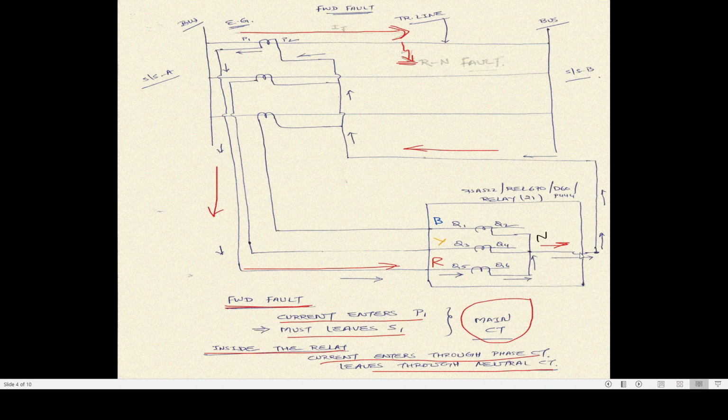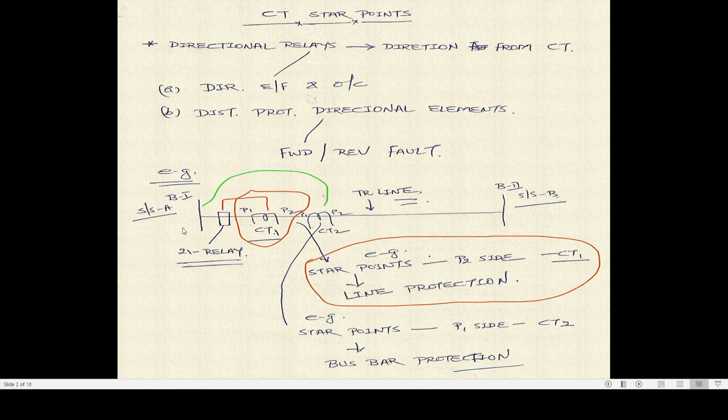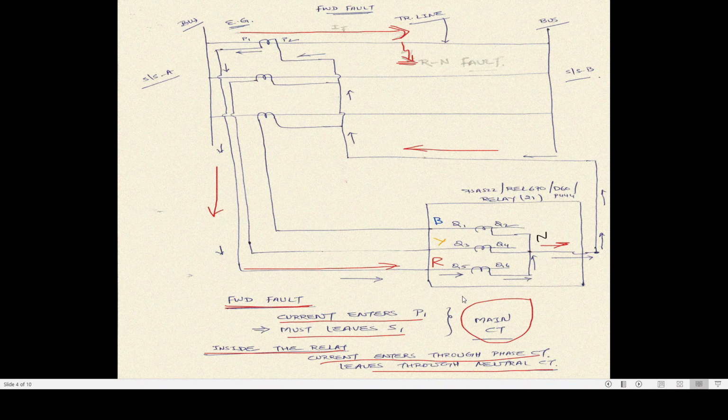Now look at here. This is your distance protection relay. This 21 relay is now magnified, and this magnified image of the distance protection relay is shown over here. Remember that this designation is exactly the same across different manufacturers and vendors of the relay. Be it 7SA522 of Siemens, REL670 of ABB, D60 of GE, P444 or P442 of Alstom, or SEL421 of Schweitzer Engineering Laboratories, in every relay the internal algorithm for current direction determination is exactly the same.